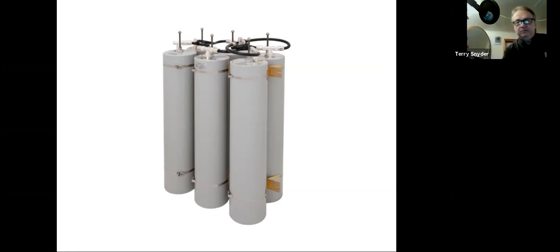And then there's another piece which this picture doesn't show. It's the coax, or the capacitive tuning, which is a trombone capacitor, which is usually about a foot long, with a plunger of a dielectric that tunes it. So you're essentially tuning your inductance and capacitance in each one of these cans to do a specific thing.